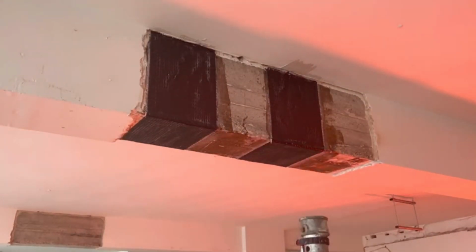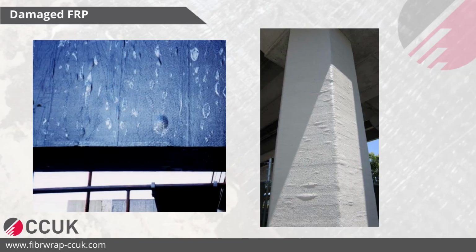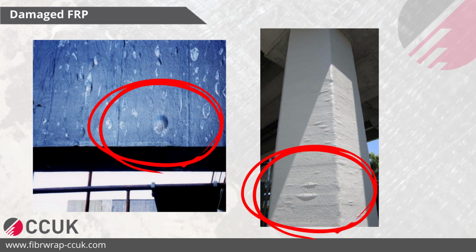So the key area was looking to avoid mistakes in that, but generally speaking, you can tell within a day or so, you can check the carbon fibre for any issues that you may have? Yeah, so if anything is wrong with the application, you will see air bubbles coming up or carbon fiber debonding or something, and all that will happen within the first few days of application.